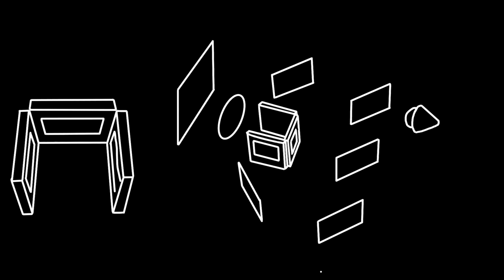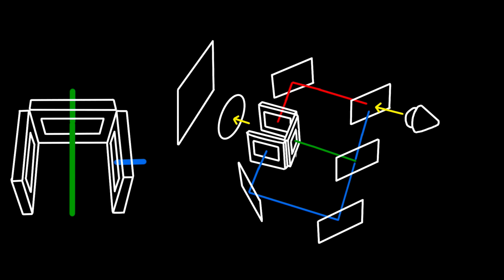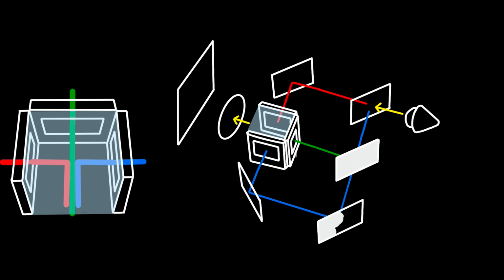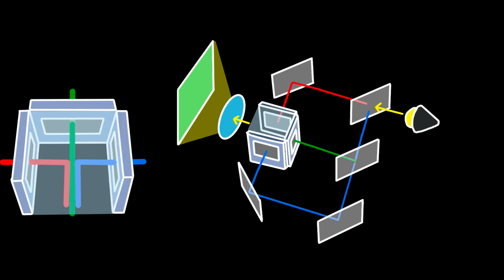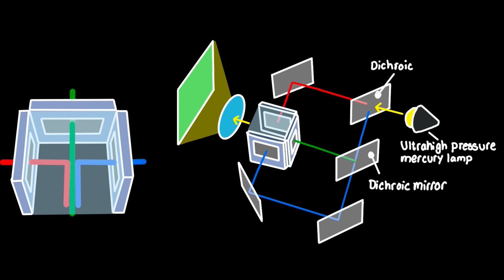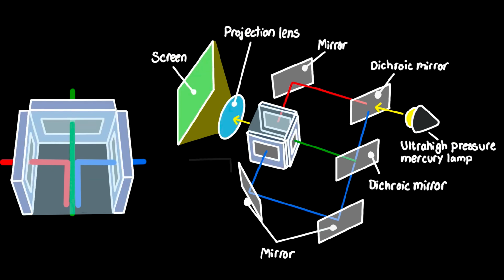In LCD projectors, white light is generated from a lamp or laser diodes, which travels through the light path and several different dichroic mirrors. It is a mirror coated in a special film that reflects only a specified wavelength of light. While going through these mirrors, the light splits into RGB, and then each light passes through an LCD panel. All three light colors are passed through a dichroic prism/cube. Four triangular prisms converge to form a single image, and then through and out the lens.